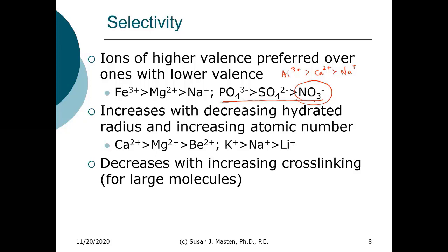So it's shifting the equilibrium from the calcium and magnesium on the resin, releasing the calcium and magnesium into that waste stream, and then restoring the resin in the sodium mode so that it can operate effectively again.